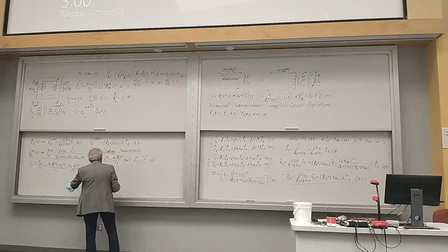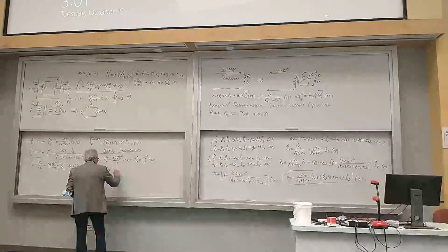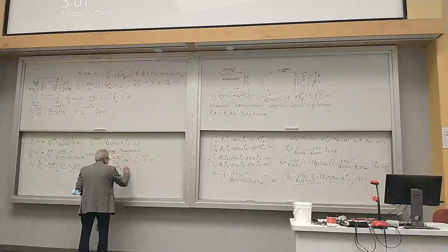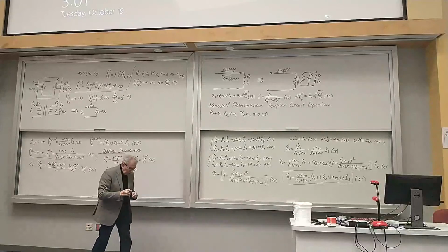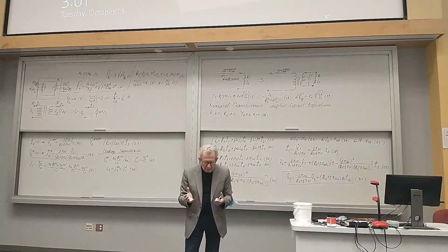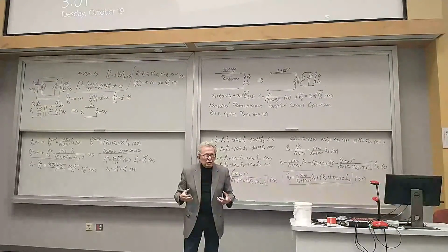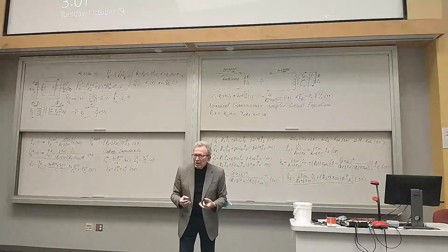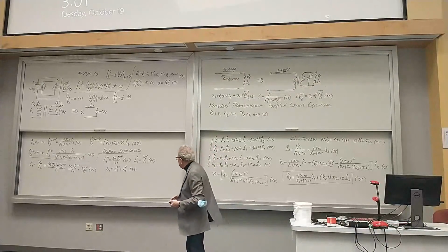And so if you substitute in this formula, you will find the result that the total inductance is the sum of the main inductance plus the leakage inductance. So in a way, the total inductance is the sum of the main inductance, which is due to most of the magnetic field lines confined to the ferromagnetic core due to its high magnetic permeability. A small number of them will leak out, they will also create flux linkages, and this will be the leakage inductance.